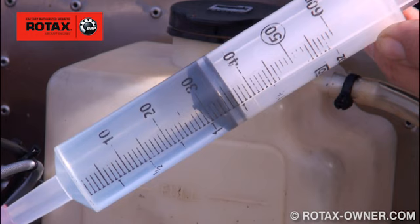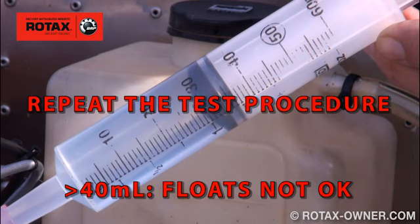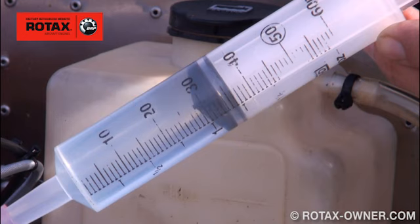If the amount is more than 40 milliliters, there is significant deviation of the float levels. Repeat the test procedure to rule out incorrect measurements. If the test result persists, detailed inspection of the carburetor and floats and check of the float's weight is required. The likely cause would be a misaligned float bracket or sticky needle valve.